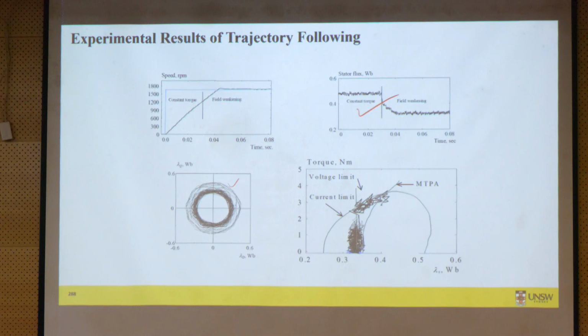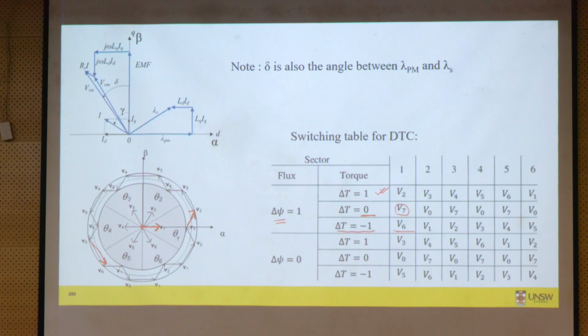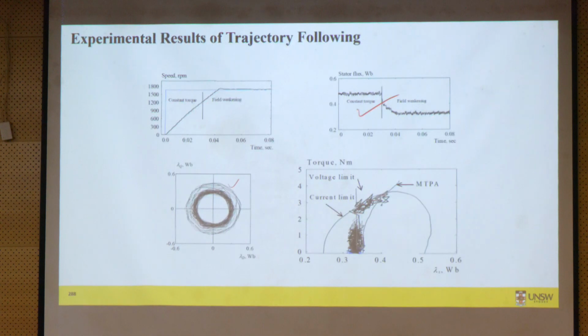Yeah, so this is because you can see here the voltage vectors are varying in a kind of band, a hysteresis band, right? And we are using hysteresis controllers, right? So because of that, you do not get a smooth circle. It varies because these are instantaneous values. You can't see a smooth circle. Theoretically we should see that, but it's not the case.